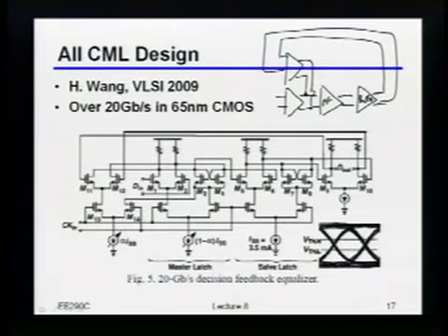Okay? There's some additional tricks they played with like bias currents and things like that. Don't worry too much about it. Really the key point here is that if you're pushing on the edge of the speed limit of the technology, then simply replacing the comparator with something that has lower swing at the output, just to reduce the number of tau of resettling, could actually be a beneficial thing to do. In this particular case, from a practical standpoint, the common modes also tend to work out relatively nicely, because now I have a CML stage driving another CML stage in terms of the current switching. These are the current switches right here. So from a common mode standpoint, I don't have to worry too much about pulling those things out of SAT and things like that.